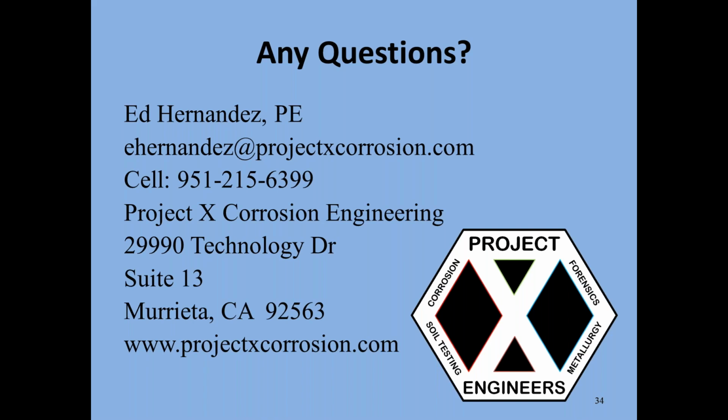So, yeah, it's a tough one, but basically we usually use a mixture of AASHTO and Caltrans corrosion rate estimations for corrugated steels and some other corrosion rate estimations based on the 40-year study from the National Bureau of Science and the Romanoff books to come up with a mixture of potential estimated corrosion rates for the zinc coating and for the steel substrate.